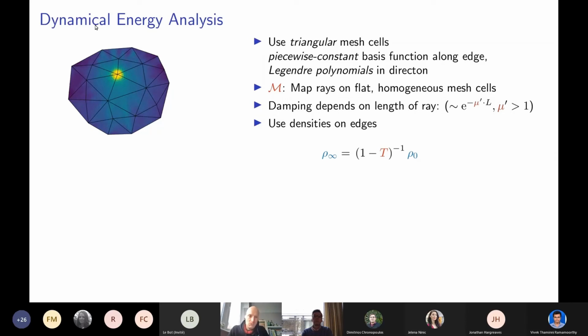So here this number was 4, so we only allowed 4 different basis functions per each side. As it turns out, as soon as you have several mesh cells, you can reduce the amount of piecewise constant functions per edge, because you get your spatial resolution not so much by resolving each edge of each triangle, but by the fact that you're resolving all of space by tiny triangles.